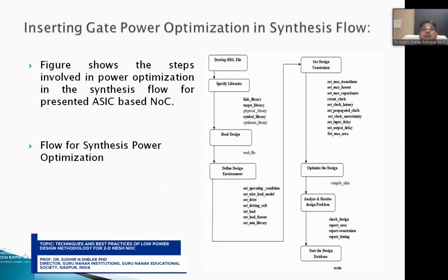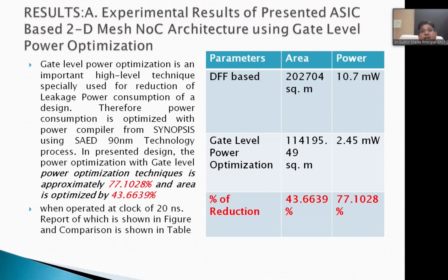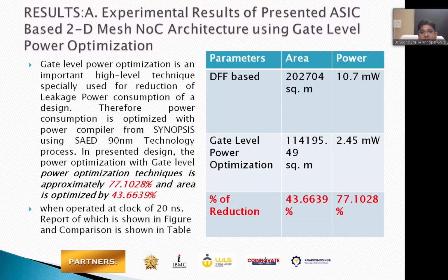So this is how we can do gate level power optimization in the synthesis flow. Ultimately, when I compare this design, the previous generic design was made using the D flip-flop, whereas in what I have used, I have used the SRAM.